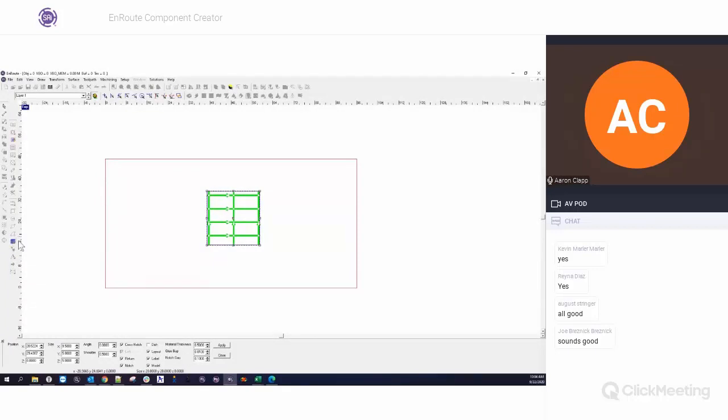When I click on this, I'm going to get a bunch of parameters down below, and then I get a grid on screen. So here is where we can choose the XY position of the grid. As we move this up and down like this, we can create the position in the X and the Y. So this is where you would fine tune that if you wanted to do that via coordinates. Now, the other thing that we can do here is define how deep, wide, and tall we want this to be. So in this first example, we'll just do a 5 by 5.